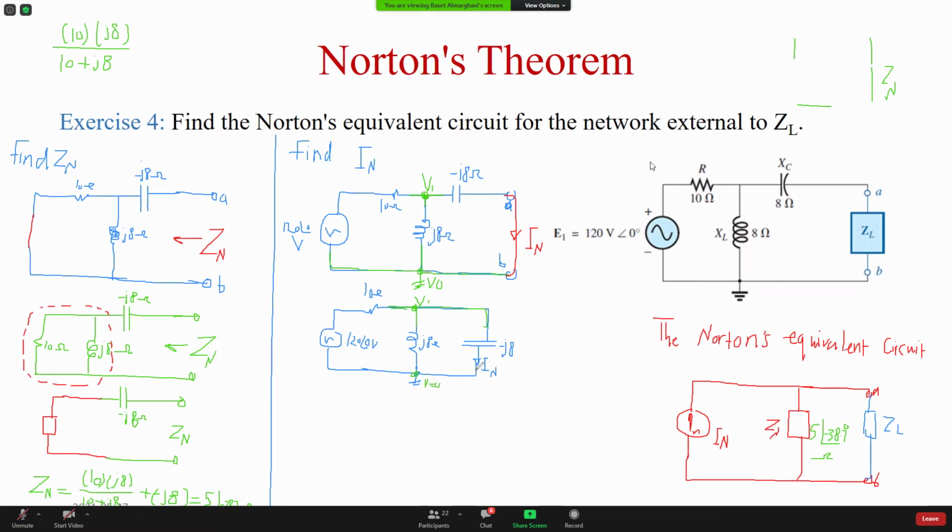I'm doing nodal analysis. 3 currents. So this is leaving this way. I'm going to say it's I1. This is leaving here. It's going to say I2. This current going that way is IN. So I just write it's IN. This is what I want, this current IN. Right, going through the capacitor, going through the short circuit to the ground. So 3 currents, they're all leaving. So 0 equals the leaving currents, I1 plus I2 plus IN.